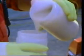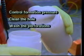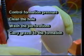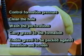The ideal fluid should control formation pressure, clean the hole, wash the perforations, carry the gravel to the formation, and enable the gravel to be packed against the formation and screen. After the gravel has been placed, the viscosity of the gelled treating fluid must break down to a consistency that can be flushed out of the wellbore.